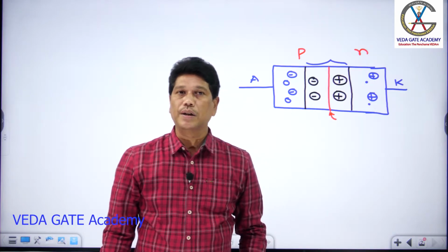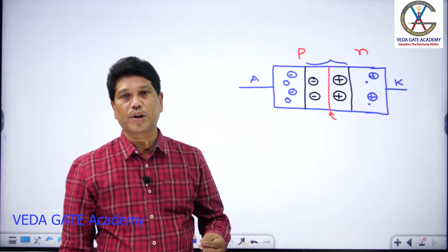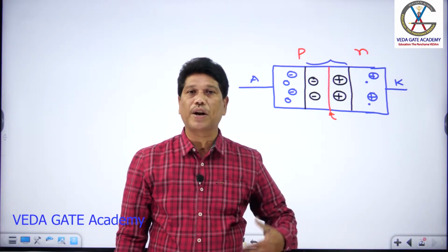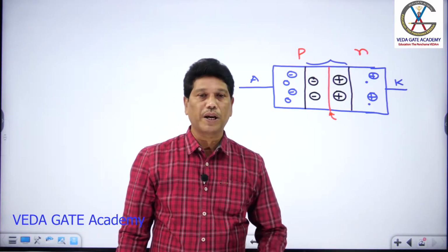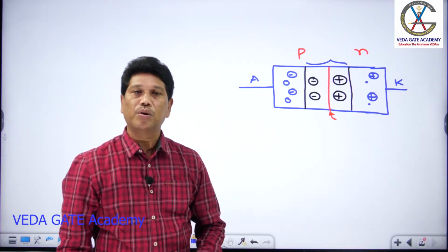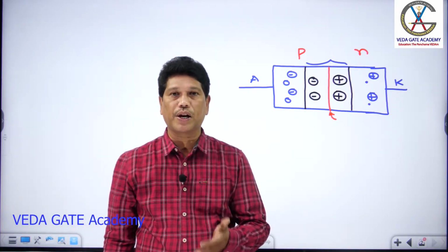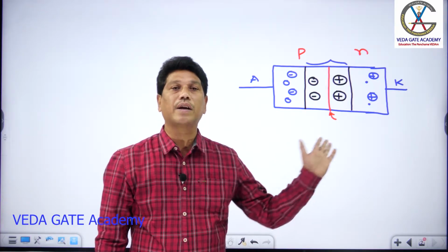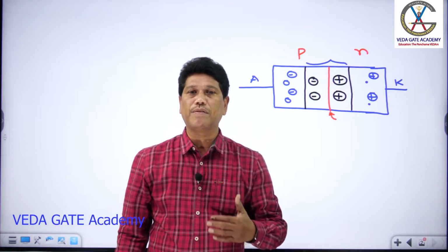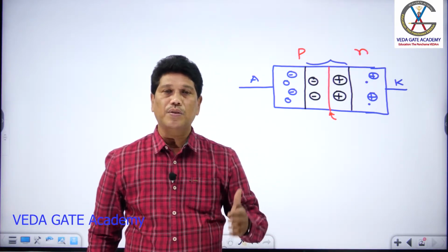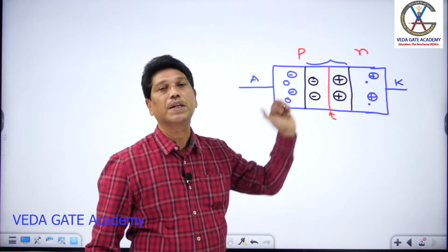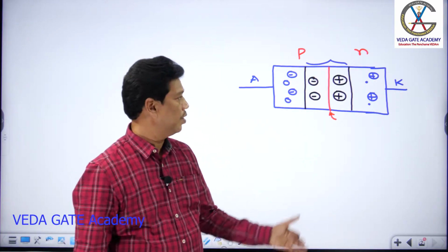Commonly you say that this internal capacitance is ignored at low frequency operation, and it is very effective if I go for high frequency applications. In our BJT amplifiers or FET or MOSFET amplifiers, you know that the gain falls off at high frequencies mainly due to internal capacitance. So it appears not only in the PN diode, but in BJT, FET, MOSFET, all of these. It is effective only at high frequency and ignored at low frequency operation, right?